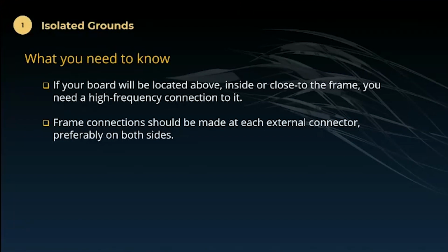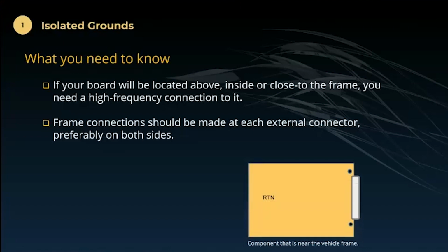And that basically means that things that leave our board, so here I'm showing a circuit board with a connector, and presumably there's a wire harness, or there are wires that are leaving that connector. Those wires are all potentially half of an antenna. If any one of those takes on a voltage at any radiated emissions frequency of a millivolt or more, we're going to fail radiated emissions, or we're capable of failing radiated emissions anyway.